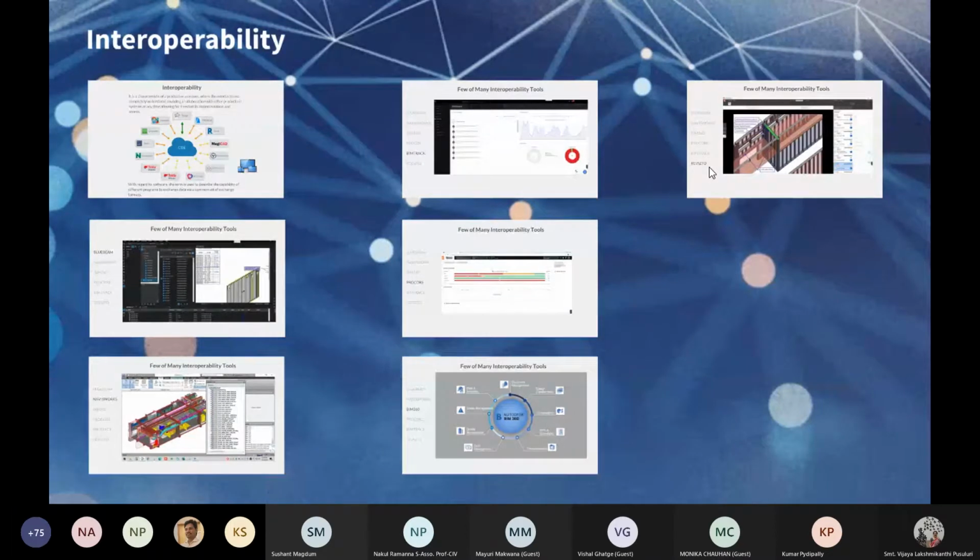But yeah, when you compare Navisworks to Revizto, going back to your question, Navisworks is an offline tool. You need to have all the files with you, and then once you have all the files, you can navigate and do all the things which you can do in Navisworks. Revizto is server based, so everyone can upload their files there. You don't need to have each and every stakeholder's files. You can view them and navigate through the model.